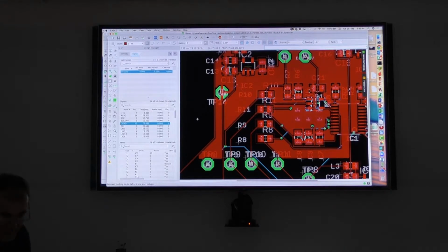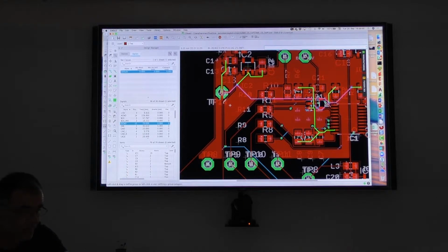So just to show you, I can switch this in the properties. How do I get this polygon again? Because if I click there, of course I don't get a polygon with the right mouse click. I have to click in the area where the contour was, anywhere there. If I don't find it, then I would recommend to switch it back into the outline mode.